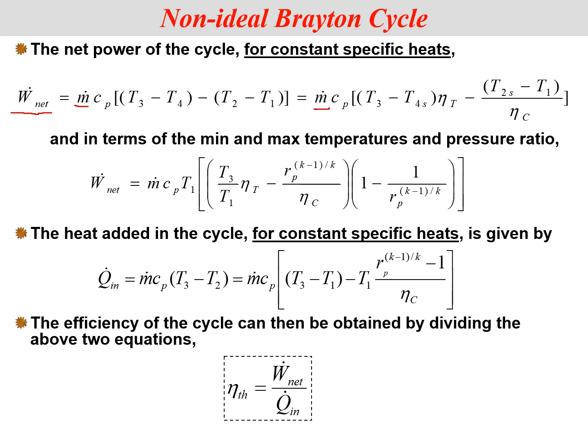So the overall power output in watts or megawatts changes with the mass flow rate of the system. The efficiency remains the same because the same amount of mass has to be supplied heat, and the same amount of mass provides you the work output.